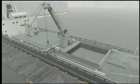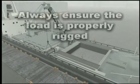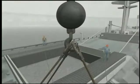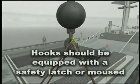The valve was not properly rigged to the hook of the crane. Always ensure that the load is properly rigged to prevent the load from becoming disengaged from the hook. It is recommended that hooks be equipped with a safety latch or mousing.